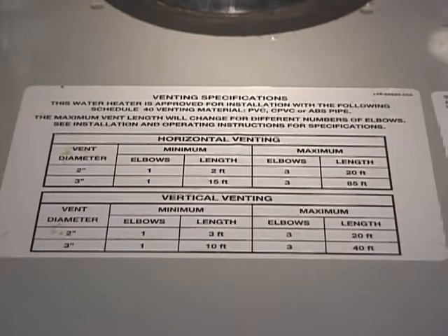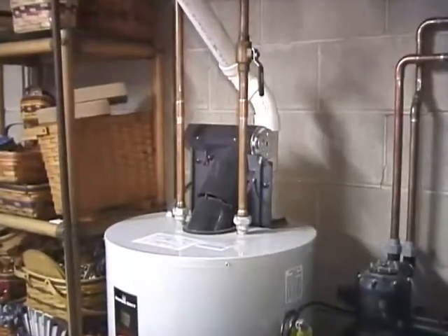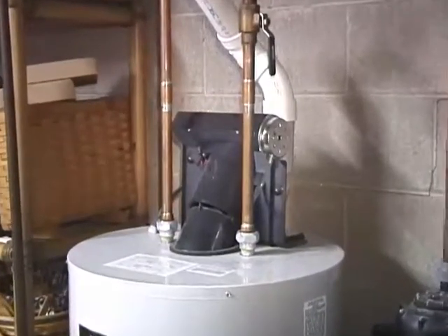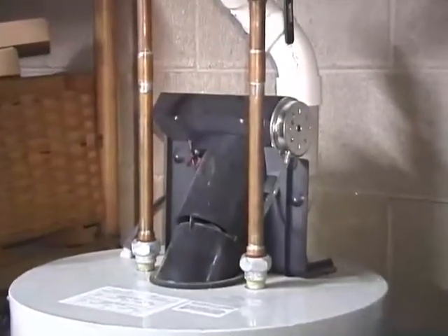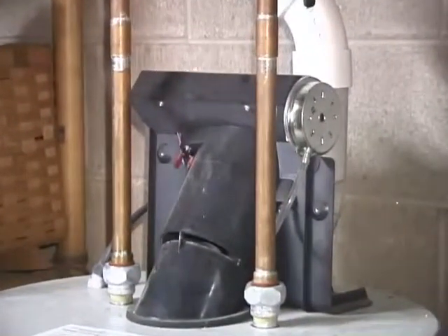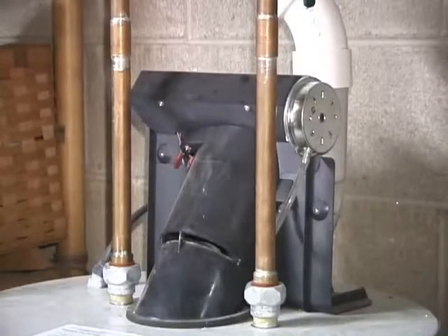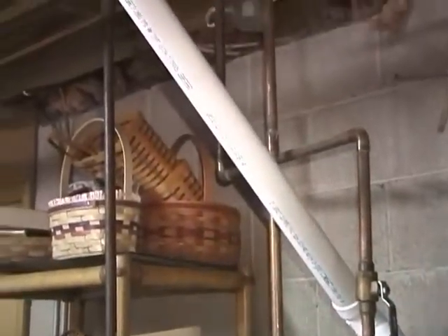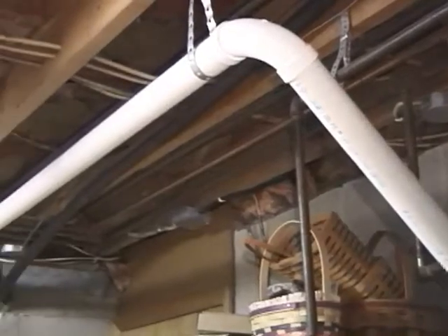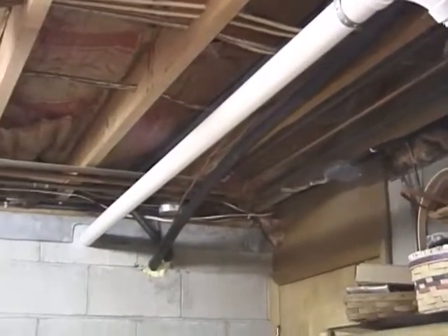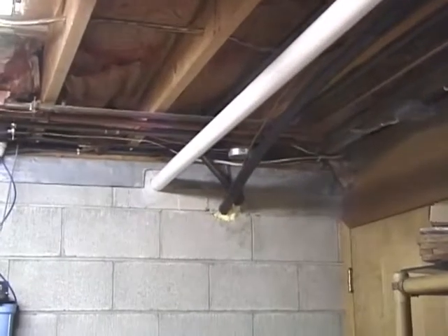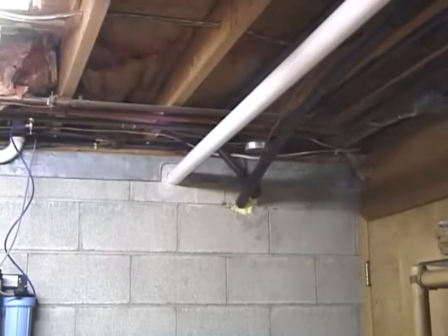These can be vented horizontally as the vent system is under positive pressure and the flue gas temperatures are reduced by the additional dilution air drawn in by the fan, rather than being reduced by a secondary heat exchanger, as is the case with high-efficiency appliances. These are an unusual type of Category 3 appliance. Because of the lower flue gas temperatures in these specific appliances, certain types of plastic pipe are allowed for venting.